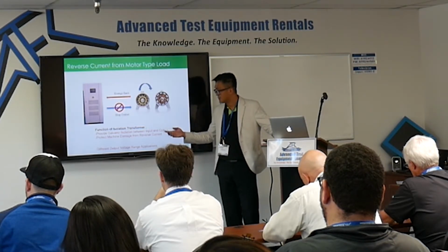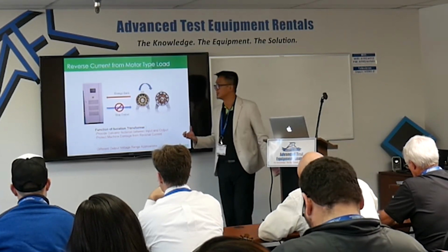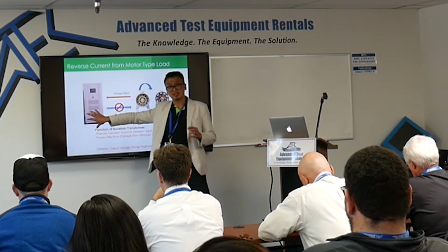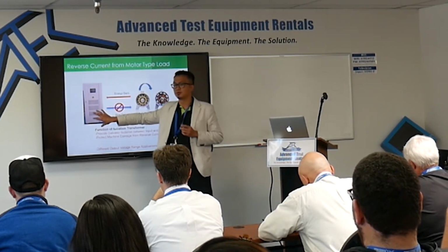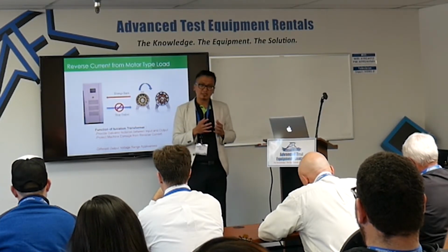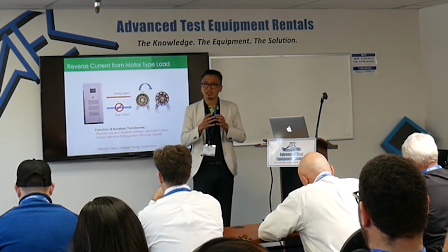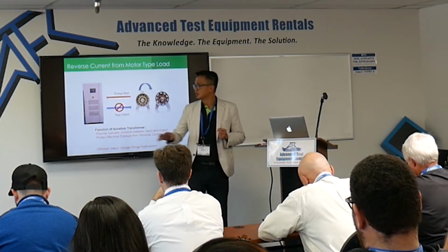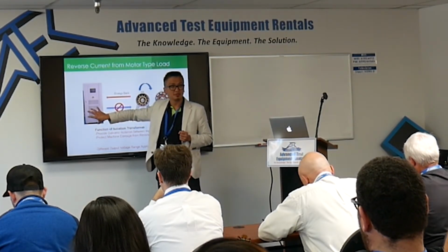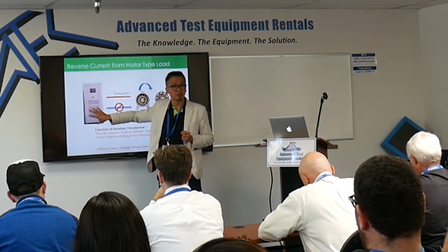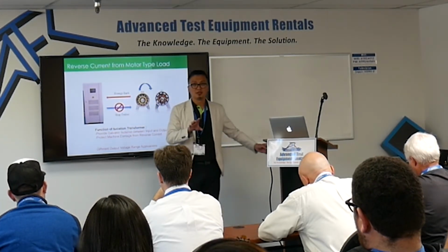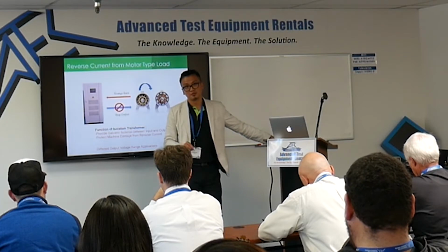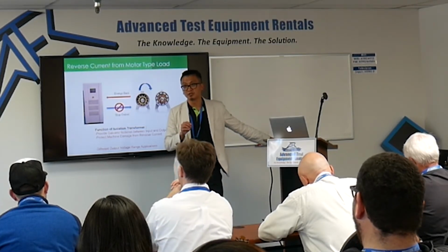The other advantage with isolation transformer is that, as I said, typically it's 0 to 300 volts. But with isolation transformer, it's easier to make for different voltage, like 0 to 400 volts. So you can still put it in the same unit, you just rewire the transformer for 0 to 400 volts. Some customers need 0 to 1,000 volts for some railway applications.